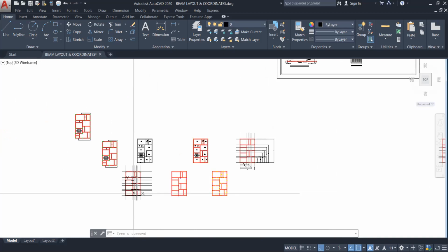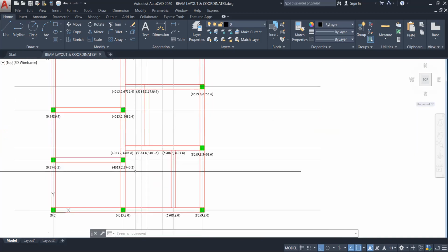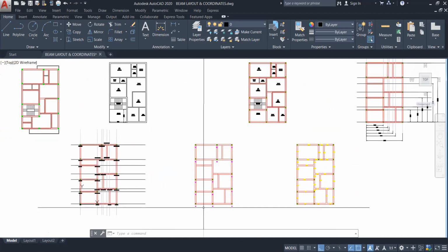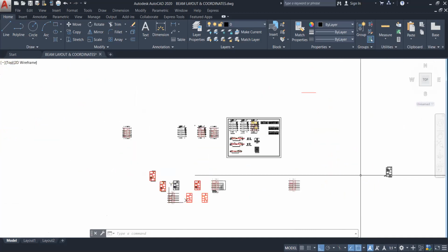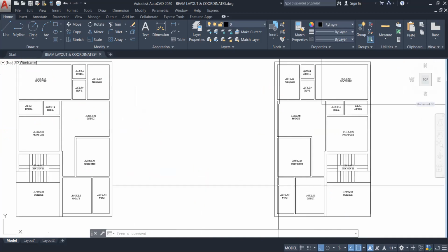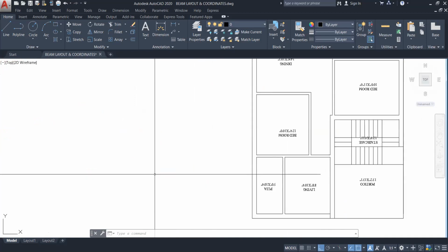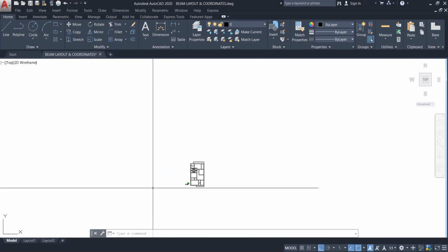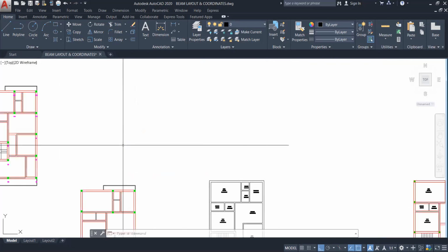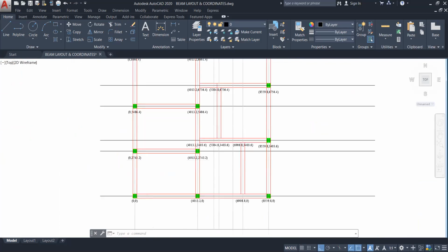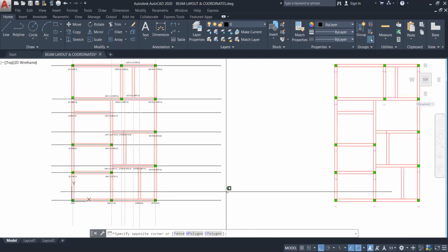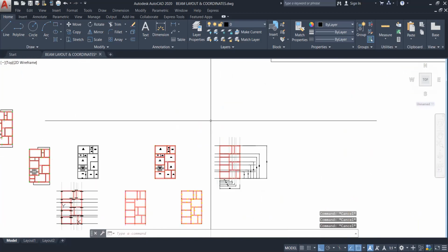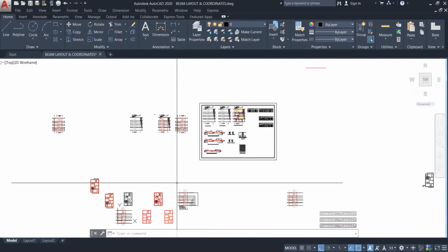The thing is, I made it for the client in feet and inches. Then I have to align it according to mm, because construction is done in mm. So you can see these are feet and inches drawings. I imported it from there, converted into mm, and placed the columns over it. After placing the columns, I marked the coordinates, then made the center lines, then made this plinth beam layout, and then imported it to Staad.